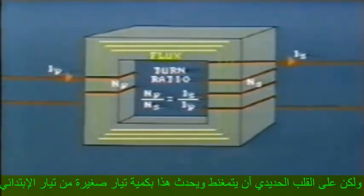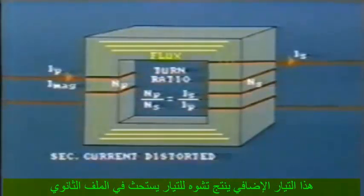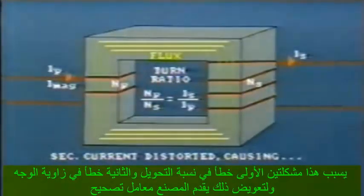However, the core must be magnetized, and this is done by using a small amount of the current supplied to the primary. This additional primary current results in distortion of the current that is induced in the secondary. Because of this, two errors occur. One, a ratio error, and two, a phase angle error. To compensate, correction factors are calculated and provided by the manufacturer.